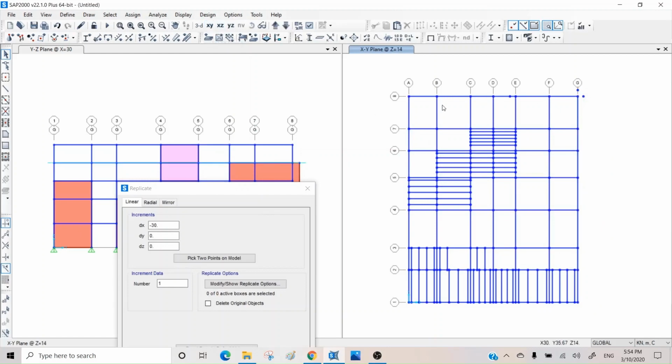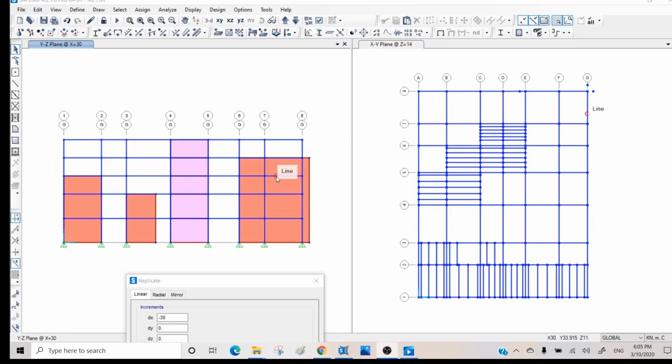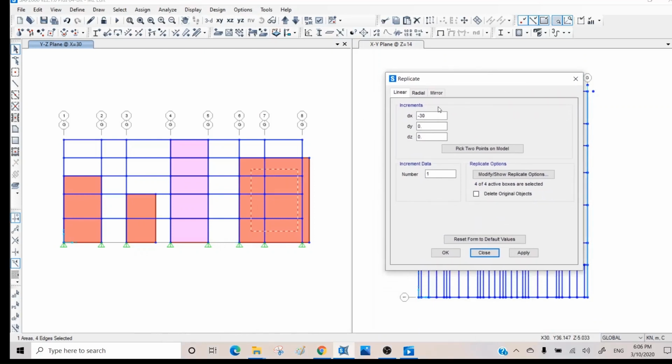So currently I'm on grid G, let's go to the plan. If I want to come to grid A, because this is the last grid, I just need to move one forward, and I can see the same on grid A. I didn't pick the 2 others, this one, so it didn't come. If I want, I can simply select this one, and the space I selected is still here. I don't need to do anything. I just need to simply apply. And now if I get back to grid A, I can see the same element here.